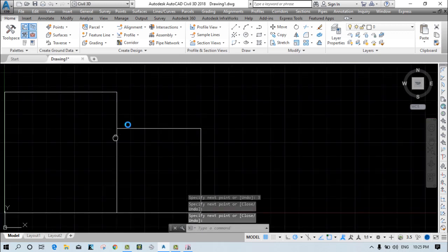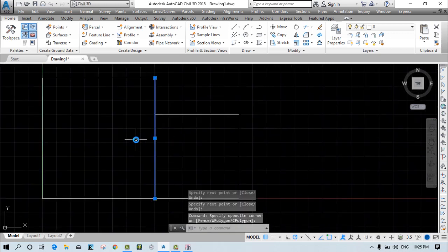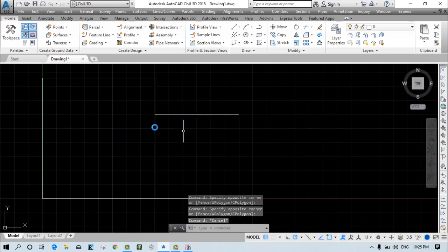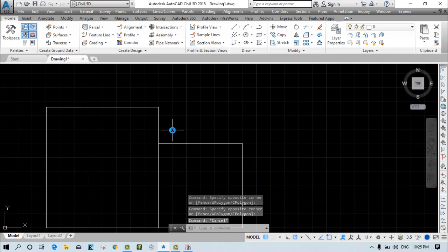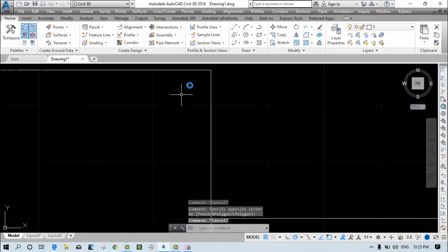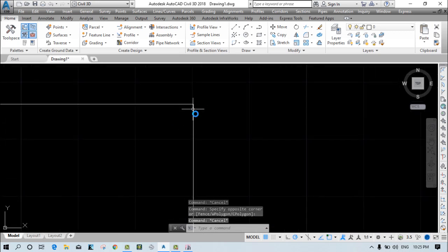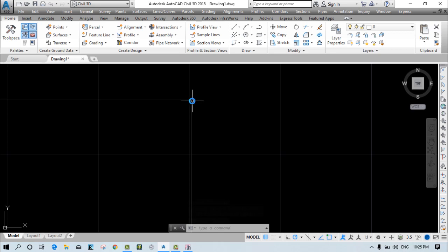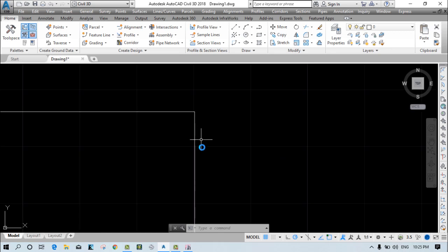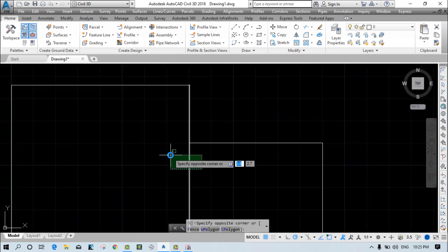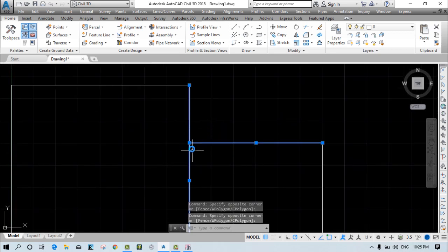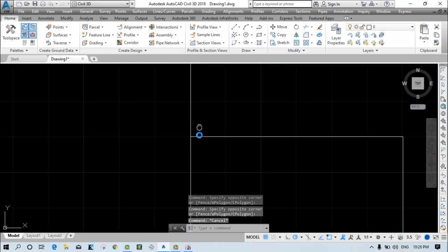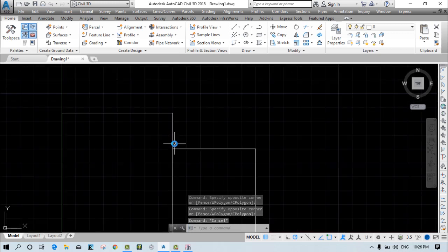Okay, but here you can see this particular beam and this particular beam. Okay, these are two different things. Even in AutoCAD, when you draw the center line plan, this particular line and this particular line meet at this point. Okay, what does it mean? It means at this point the column position will reflect. Okay, at this point the column will be generated. But you can see that here also the two beams are adding. Okay, so you need to break the beam in STAAD Pro.